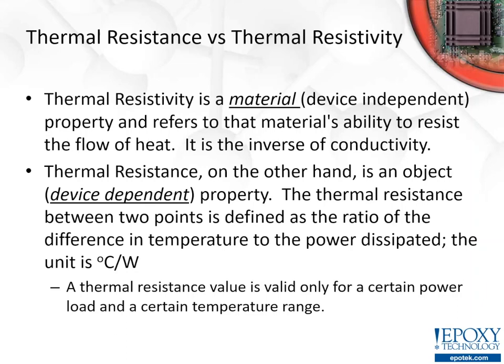We have pushed the thermal resistivity of our products as much as we could, but as we continued to interact with customers and have things tested in device, we realized that truly thermal resistance, the ability of the material to actually dissipate heat in device, was the critical property, and that thermal resistivity or thermal conductivity and thermal resistance were not necessarily correlated.